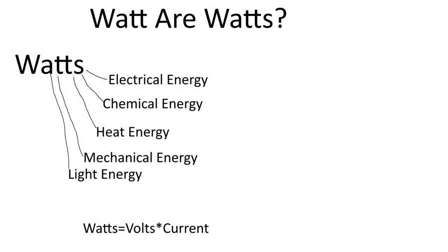And then we take our current and multiply it back by the voltage to find our total power in watts. Meaning, volts times amps equals watts. Yes, a new unit, watts. It has direct conversion to heat power, like an air conditioner circuit or a heating circuit. Light power, like in a lighting circuit, like in your house or in a flashlight, or mechanical power, like in motors.